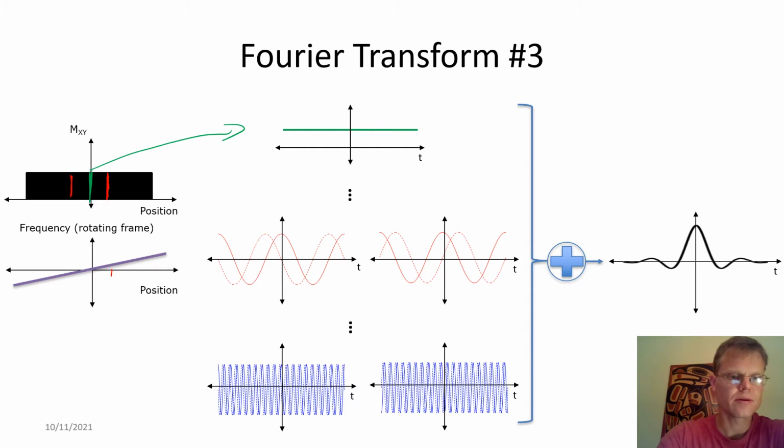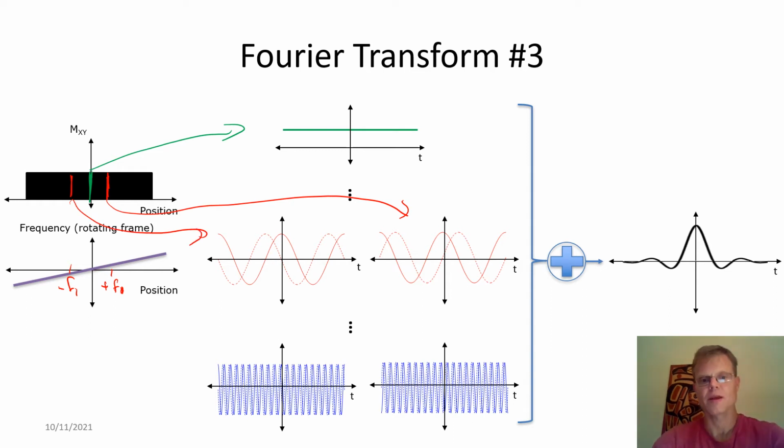Now, note here I'm using a concept. Let's call this a positive frequency, negative frequency. So one of these is going to correspond to each of these two sinusoids. These are complex exponentials, but as you can see, the imaginary component is flipped around. That's the difference between a positive frequency and a negative frequency in a complex exponential.